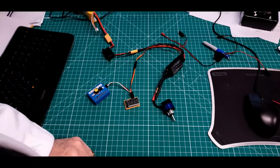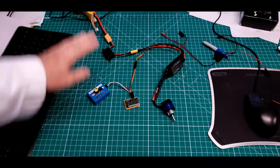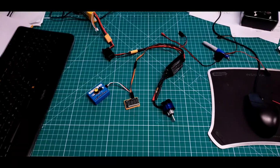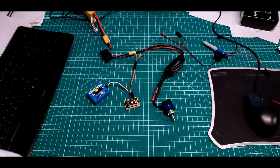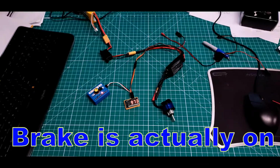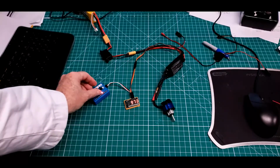then it should just basically beep and tell me what cell battery it sees connected to it and that sort of thing. It's a 3S battery, so there should be 3 beeps out of it when I turn it on again. 3 beeps, and then a short single beep telling me it has no braking turned on in this ESC. That's a different subject. What we were interested in now is what happens when I turn this dial now.